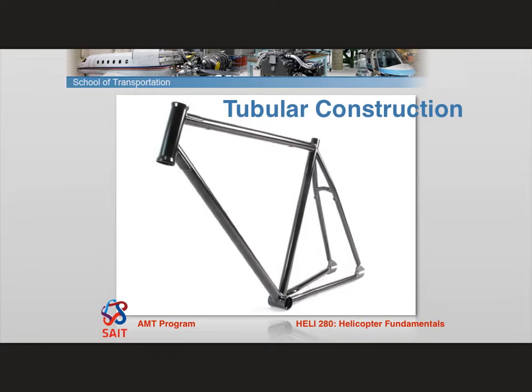It is possible to repair some of them, but if you do repair them, you need a jig. Now, some manufacturers like Robinson pre-stress their frames, so those ones you can't repair, but other manufacturers with a steel tube frame, you can repair it, but it's got to go back and be repaired in a jig. It's not just something you can do in the field.